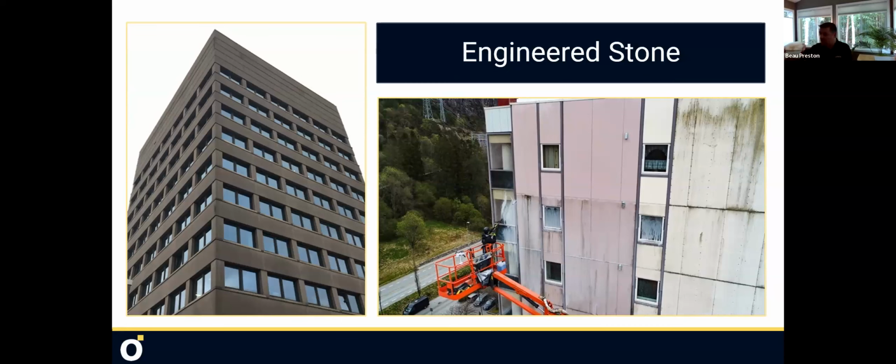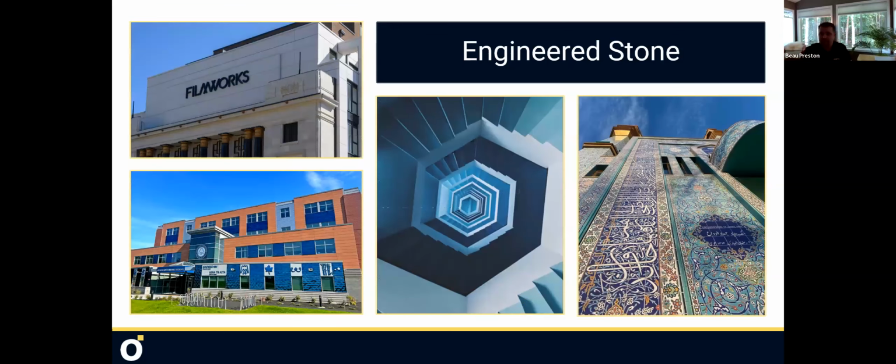Engineered stone rain screen facade. The one on the right, we showed you the video earlier of them cleaning that. That's after 30 years. Look at the color. The color, although it's not a beautiful color, it's consistent. The one on the right, when you clean that and when you see the rest of the video, it's pearly white again. Any other white panel on the market, if you were to do that 30 years later, it would either be stained permanently or it would be faded disproportionately, because that mold and mildew would actually block UV from something, say like a phenolic. Okay, so having this consistency is a real big deal.